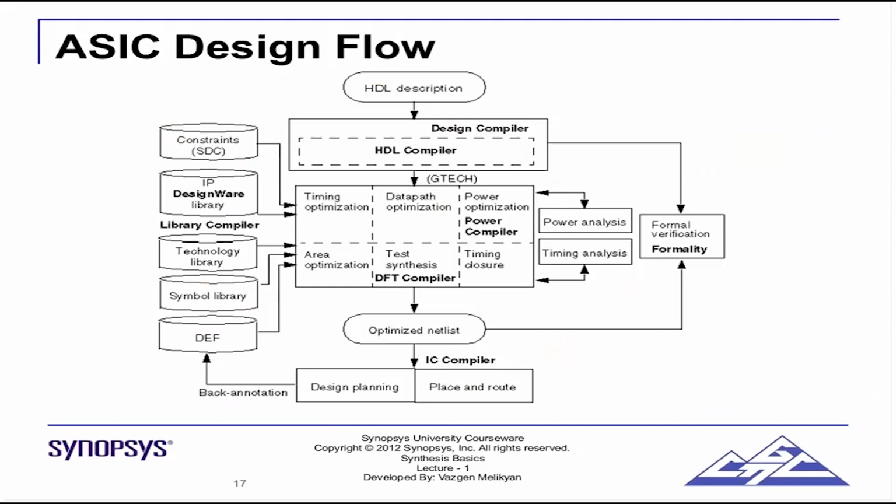Now we would go and finalize the architecture. What type of registers will it contain? What frequency are we targeting? That will in turn decide what technology node we should choose, and so on. Then we will start coding. So we'll start writing the microprocessor code in Verilog, which is the HDL description.